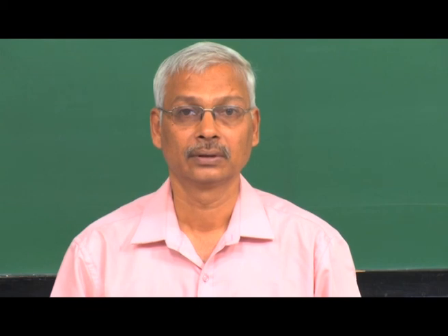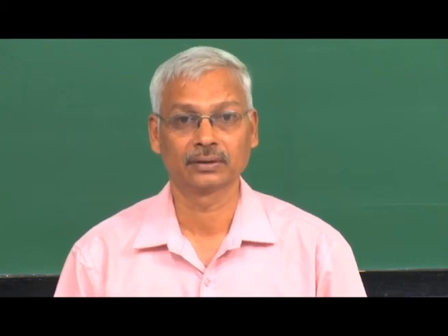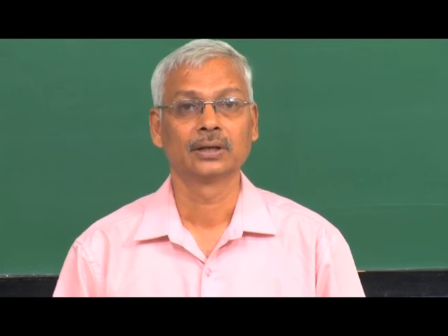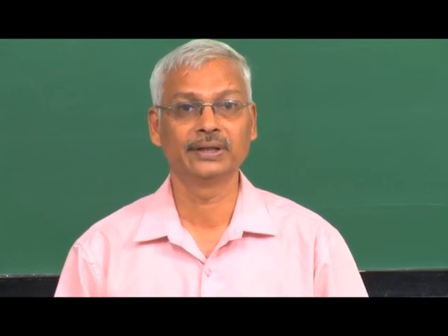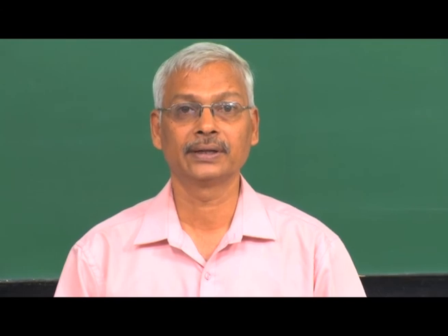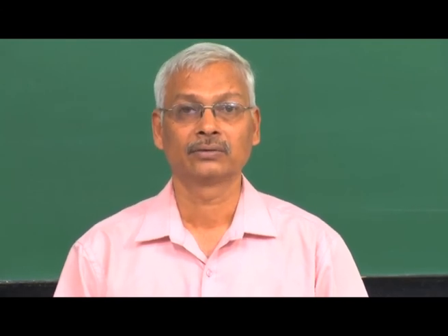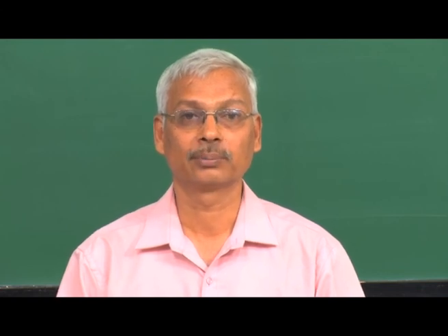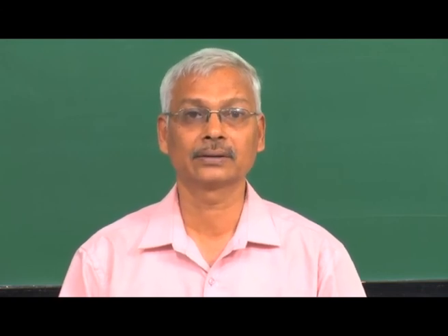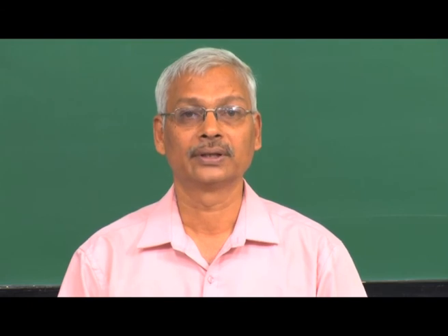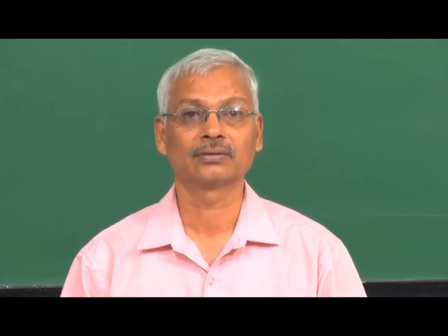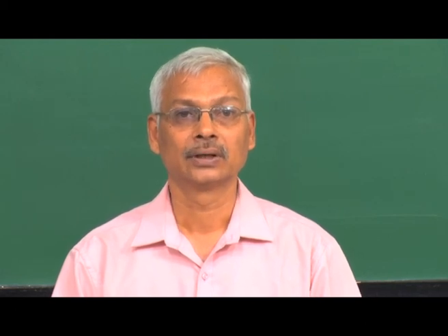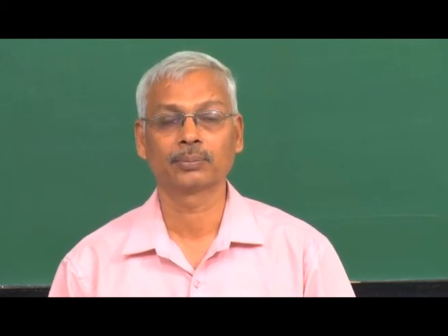And now, let me summarize the topics covered in this lecture. We discussed the meanings of taper, tilt and angle. We also learnt about the various instruments used for measurement of taper and angle. We learnt about the combination set, the vernier bevel protractor, and the optical bevel protractor.